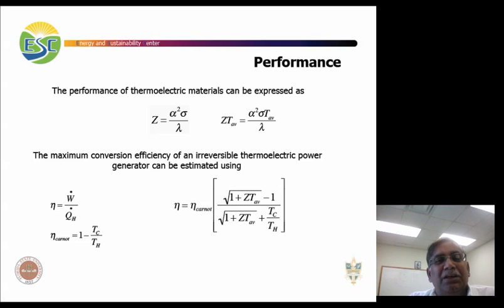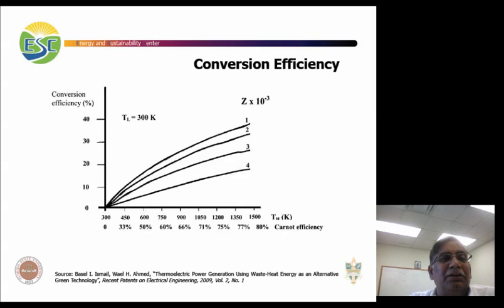And you can see the total efficiency then is proportional to, in this particular case, ZT, the square root of 1 plus ZT, this parameter G, and then the TC and TH. So the trick in all this is to find higher values of Z sub T, and then we'll get a better total performance of the system.